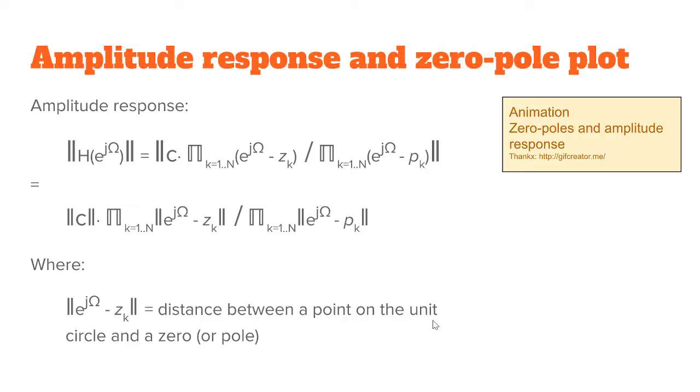And yes, you can actually do this. Some years ago, we had a lot of fun. We had a parallel calculator. Each one of you had a different angle, and we calculated the amplitude response using this. But okay, we have MATLAB also, so it's a little bit easier that way. But the meaning is quite straightforward. It's the product of distances. The numerator is the product of distances to the zero points, and the denominator is the product of distances to poles.